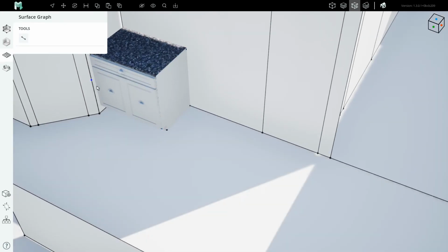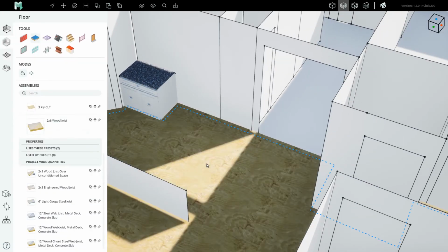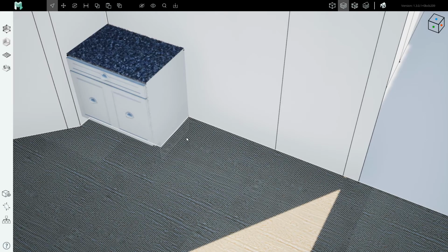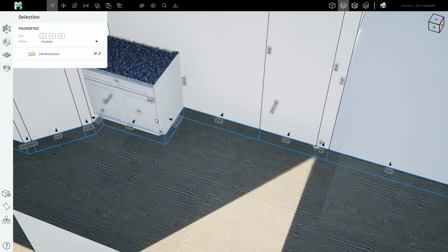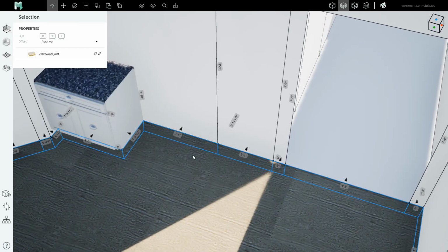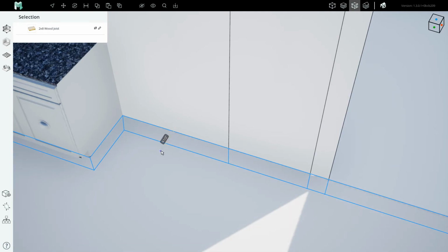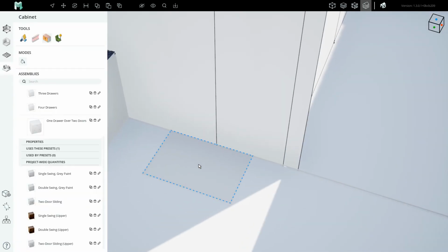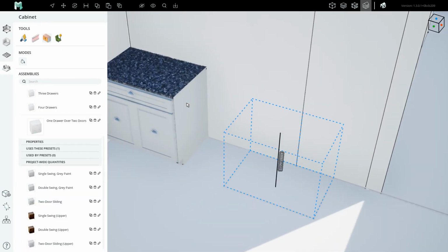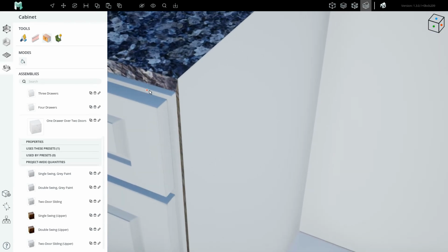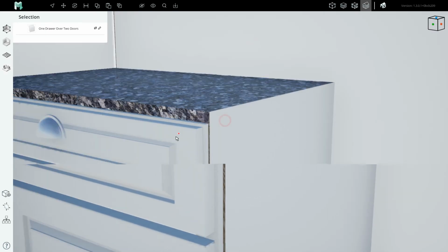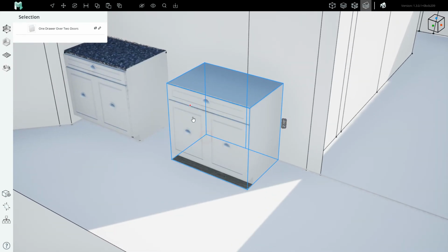If I were to go over here and make a surface graph, I'll add a floor. This is the grand finale. I'll make the 2 cabinet types side by side. Here I've made a floor that comes to meet the base of the cabinet. I now am putting a surface graph on it. I will now create a surface face that is 2 feet deep by 3 feet wide. And come back. With this patch, I will now make a cabinet that is very, very similar to my previously created cabinet. I'll snap to the underside of the countertop, somewhere around there, and I'll pick the front face.